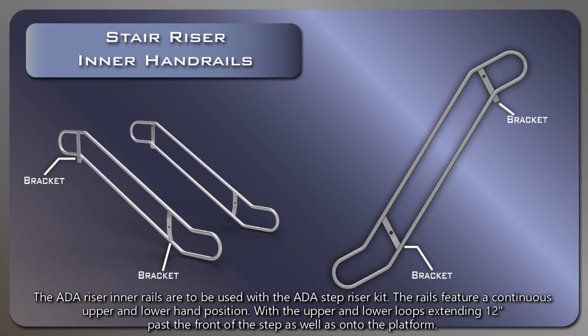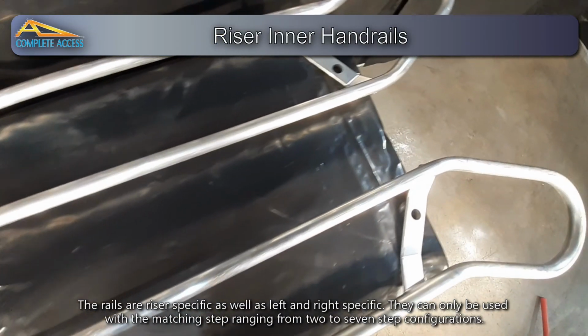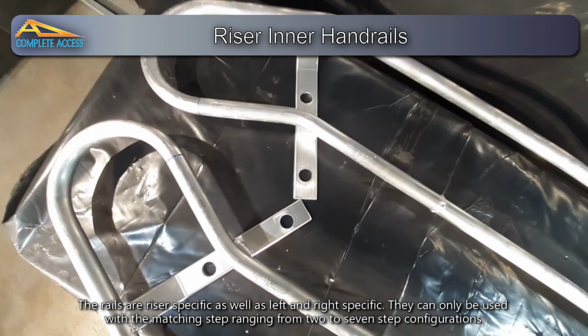The ADA riser inner rails are to be used with the ADA step riser kit. These rails feature a continuous upper and lower hand position, with the upper and lower loops extending 12 inches past the front of the step and over the platform. The rails have two brackets. The upper bracket contains two hole positions to accommodate the upper and lower positions of the step platform. These rails are riser specific and also left and right specific. They can only be used with the matching step ranging from 2 to 7 step configurations.